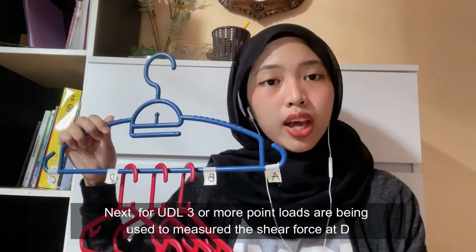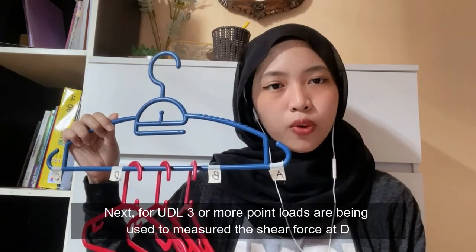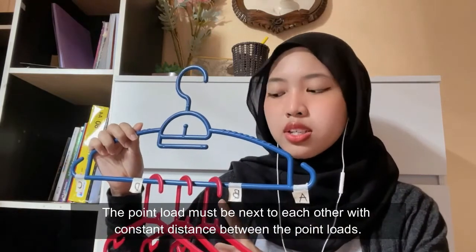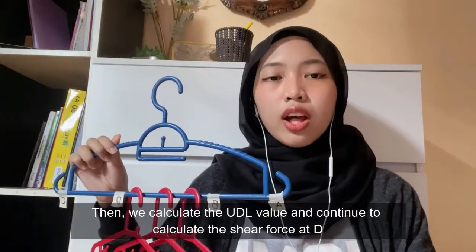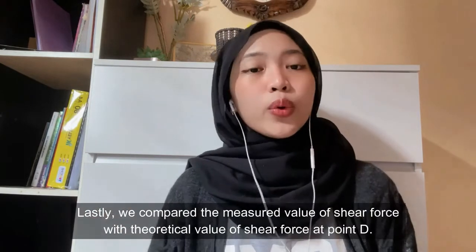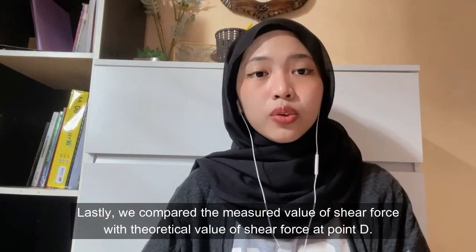Next, for UDL, 3 or more point loads are used to measure the shear force at D. The point loads must be next to each other with constant distance between them. Then, we calculate the UDL value and continue to calculate the shear force at D. Lastly, we compare the measured value of shear force with the theoretical value of shear force at point D.